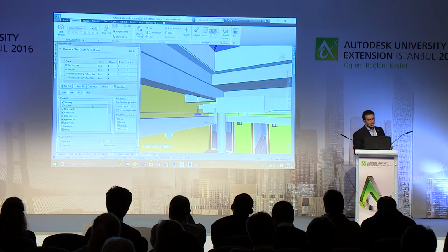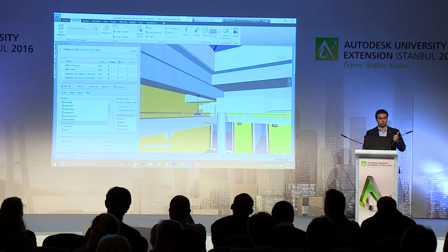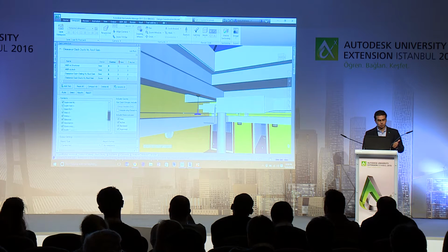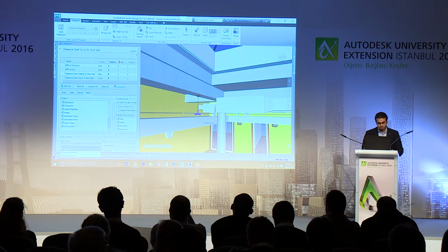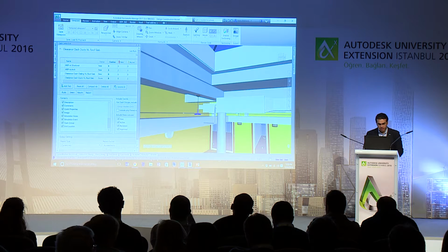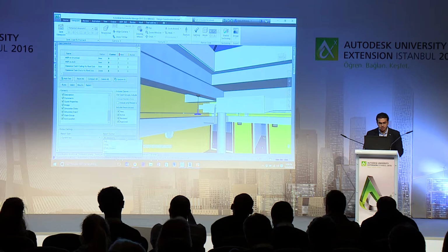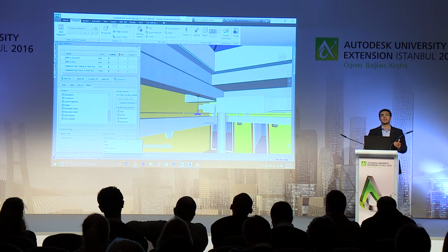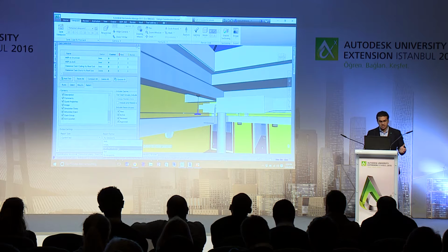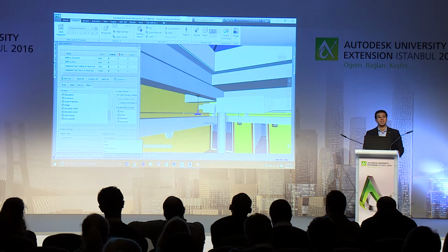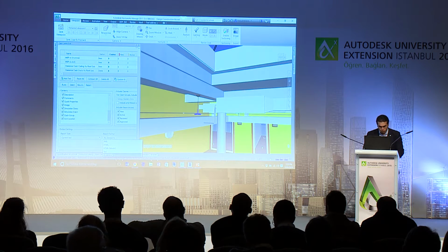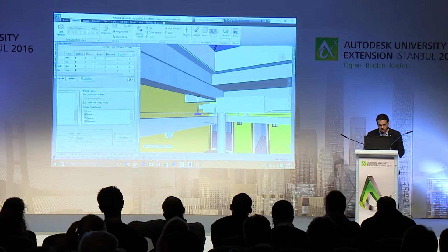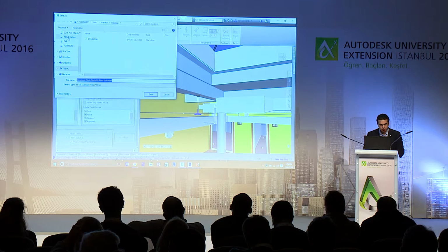Inside of Navisworks, you have a greater flexibility to control what's the content of the clash report that you want to extract. You can export one test or multiple tests at a time. And also, you have the flexibility to create your report in multiple formats: HTML, XML, or text, or save the results as viewpoints. So one example here, just to show you the difference, is to export it to an HTML format on my desktop.